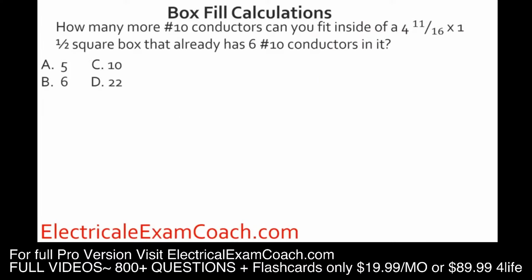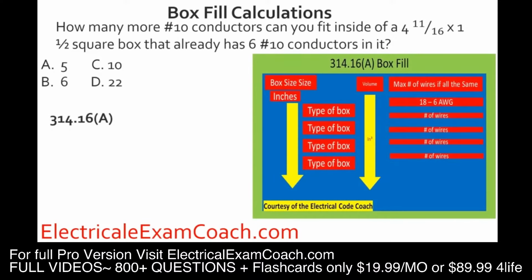How many more number 10 conductors can you fit inside of a 4 11/16 by 1.5 inch square box that already contains 6 number 10 conductors? Well, since both of these are of the same size, we can just do some simple math. First, we have to find out how many the box holds at all, and we find that it holds 11. We already have 6 conductors, so we take our original 11 minus 6, and it lets us know that we can put 5 more inside of that box, and we select A.